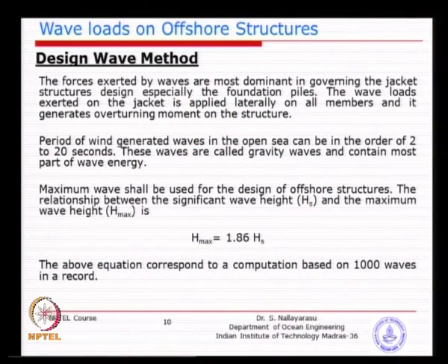It's moving water. Most of the east and west coast we get wave periods of about 12 seconds. The maximum we have seen is a 14-second wave during a cyclone period, but other than that normal periods are around 10 to 12 seconds. So, if you go to the beach you will see that every 3 seconds a wave is approaching and breaking. They are all just seasonal waves, but if you look at a storm wave, it may take 10 or 12 seconds before you see the second successive crest come and break. So, that is the difference between seasonal waves versus storm waves.